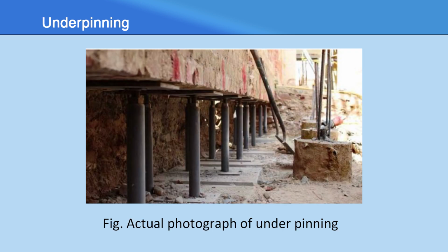Next topic, that is underpinning. What is underpinning? What is its purpose and application? So, first of all, definition. Underpinning is the process of strengthening the foundation of an existing structure by extending its depth or breadth. Purpose: to stabilize the foundation that have settled or are unstable, to increase the load bearing capacity of existing foundation,